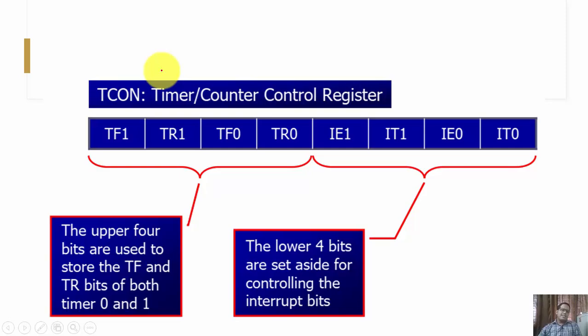The next register is the TCON register. TCON stands for timer or counter control register. Basically, it is again an 8-bit register and it is bit accessible. Means with the help of some instructions, we can directly set or reset individual bits of this TCON register.